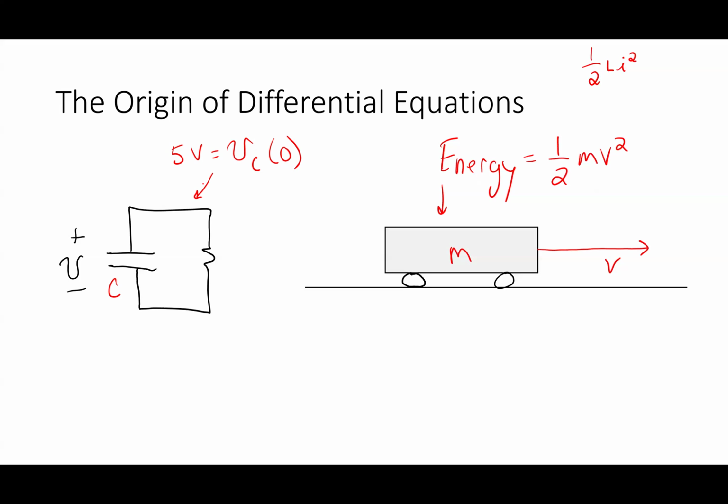What's happening? The energy stored in the capacitor is basically being lost in that resistor. And if that resistor was 0, it would be gone immediately. But what will it look like over time if I looked at that voltage on that capacitor? It'd start at 5 volts, right?